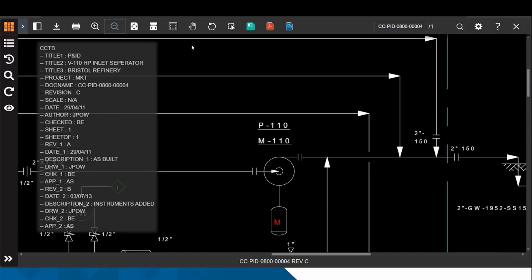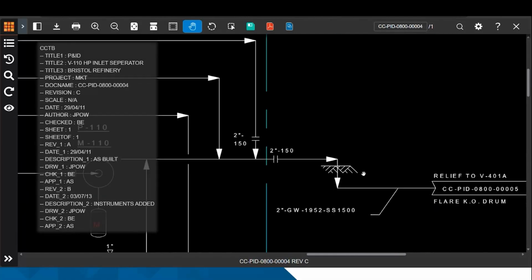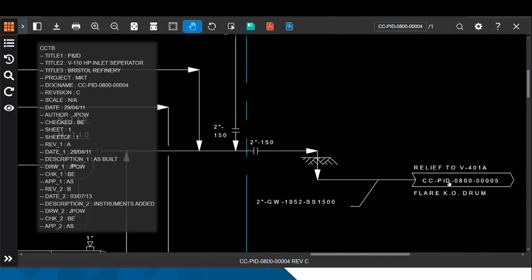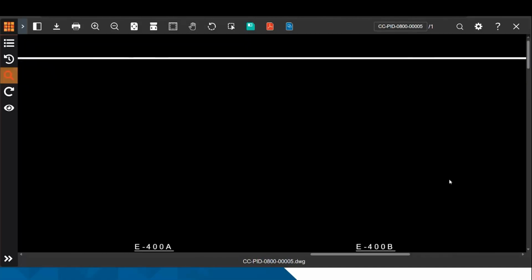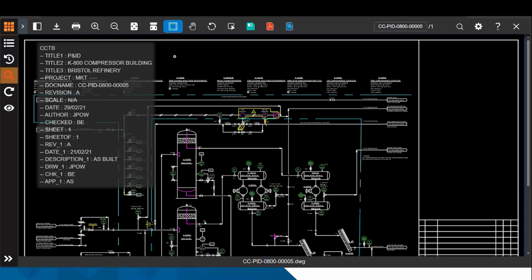What you can also do is, if you're looking at this pump, you might want to walk the line and say, okay, on drawing 4, I want to see what the downstream implications are for anything I do on this pump. So I'm going to go to the next drawing. We're on drawing 4. We can click on this continuation tag where it says that the line is continued, and it will open up that drawing and give you direct access to the information in that drawing. So this is opening up drawing 5, and again, you'll also be able to see where you came from.